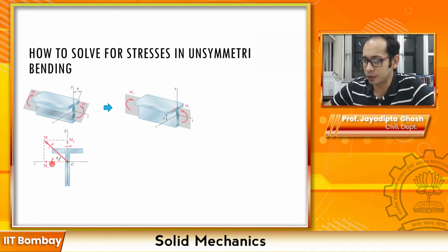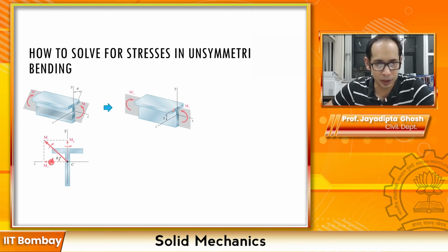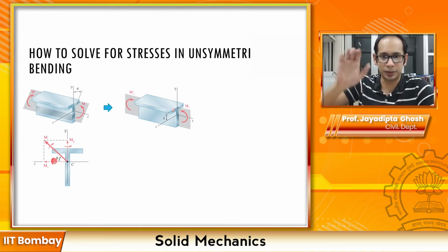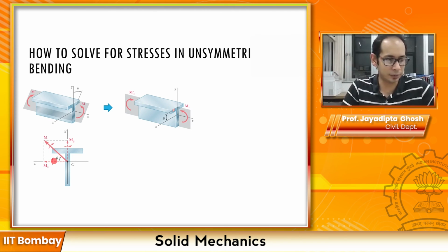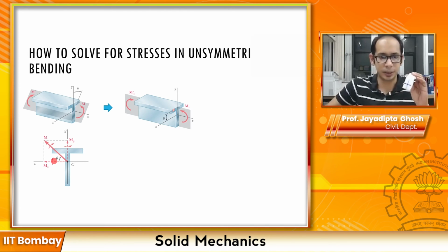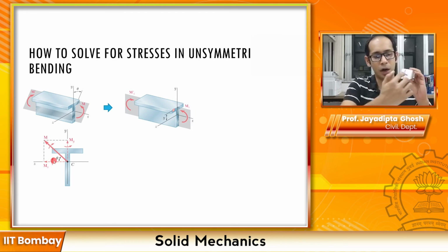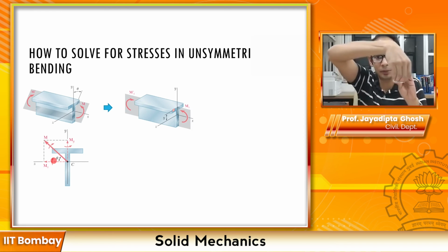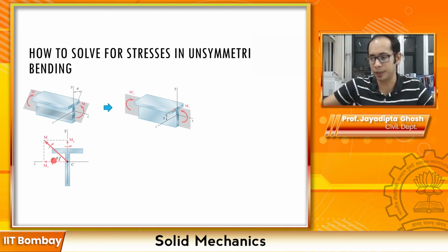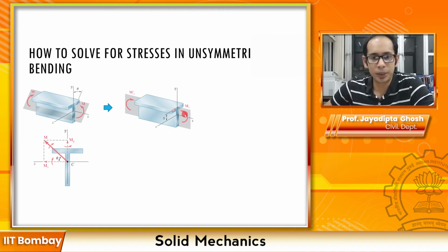So for the first one, this is the Mz over here, which is acting like this. And why is it acting like this, you may ask. Mz is pointing towards that. Now follow the arrow and the curved line over here. It is pointing like this, right? So that means that if this is my zz axis, this guy on the screen is marked like this with the finger curling. So that means my beam is bending like this over here, right? The beam is bending like this. My finger is curling like here. So this is how the moment is acting, Mz.